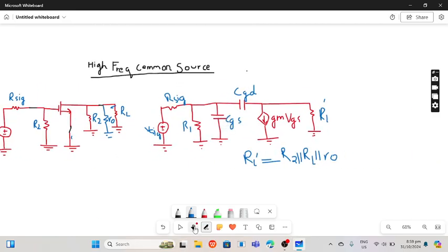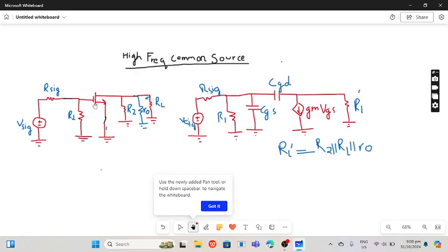So this was the whole procedure behind it. We short all capacitors, and the common source area is grounded. You will see that it becomes grounded. In most cases a resistor is connected with a capacitor in parallel, but I straightly connected a capacitor and grounded that one. This is your drain part area. Here R2, RO, RL are in parallel. We replace it by this, and after that we replace it with the pi model.